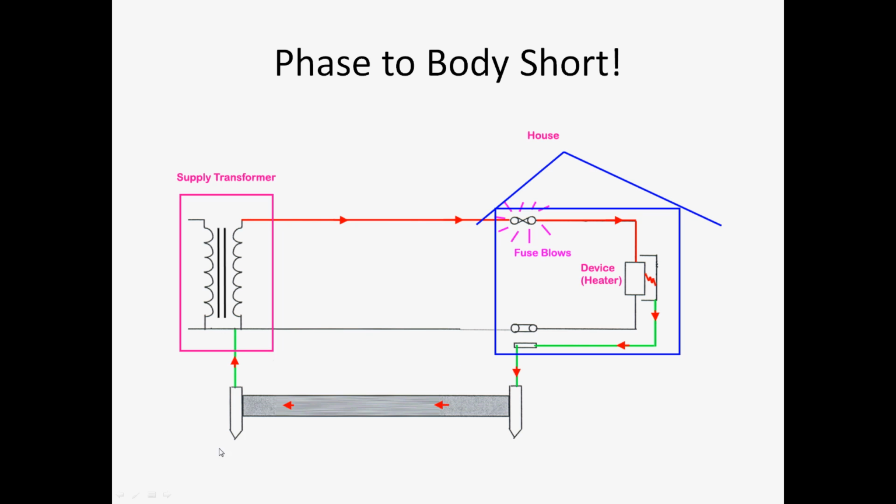In this system, the earth wire is terminated at the load side earth electrode, and it doesn't continue to the transformer. This system is called TT system. These are just some extra points. The main point is the current will complete its path through the transformer through this path.